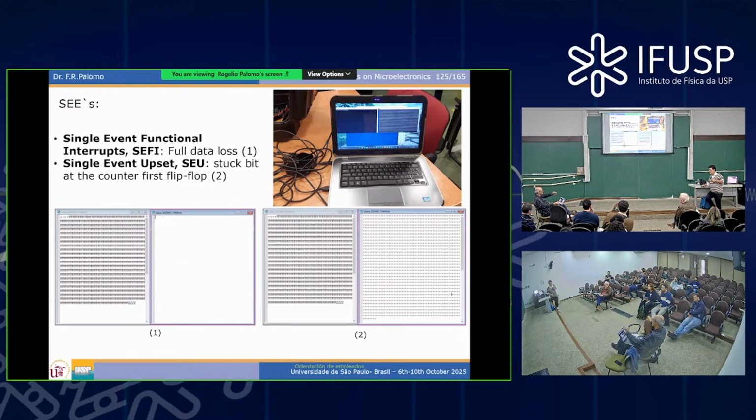Again, very simple. We are looking at single event upsets, not at single event transients. Sure, you have a lot of transients there, but the reading we are doing is insensitive to single event transients. What we are looking at is just ones or zeros, coded as Fs or Zs, because it was easier to look at, in the RAM memory we implemented.